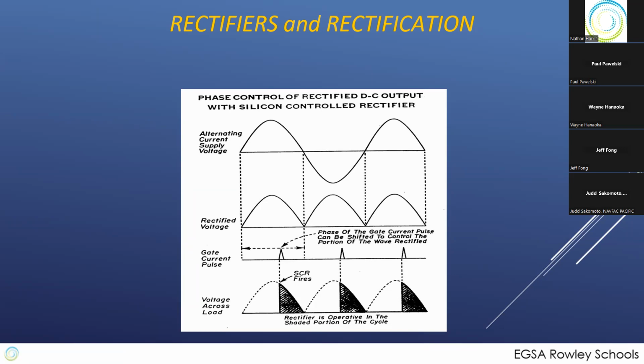So you've got to spend a lot of maintenance time making sure that corrosion and physical flexing from heating and cooling and a dozen other things haven't ended up causing your grounding to be incomplete. And even if you do that job correctly, all it takes is for the door to be open at the time the EM pulse hits, because someone's coming into or going out of the building, and the whole thing is fried.